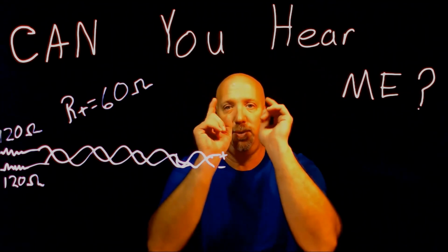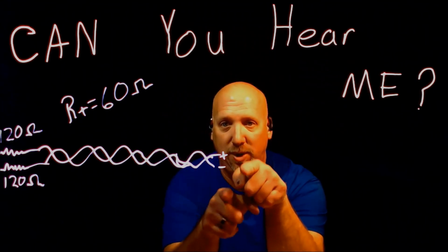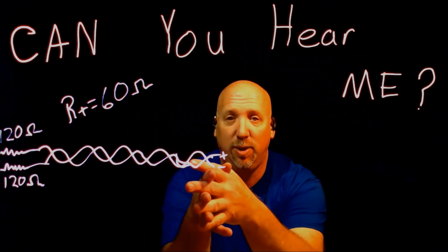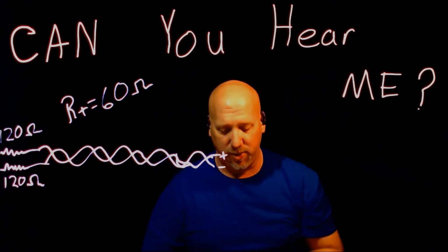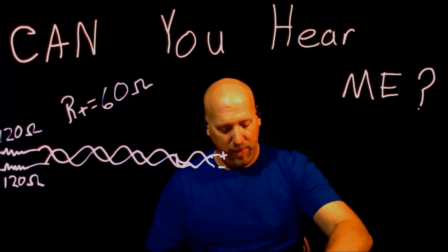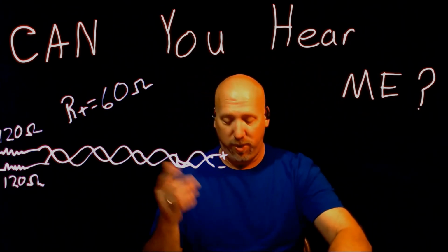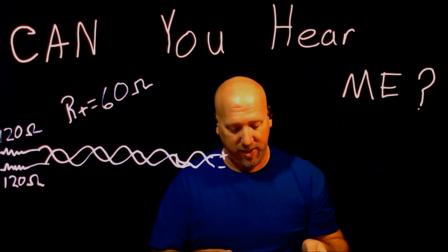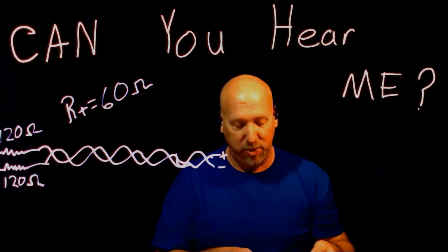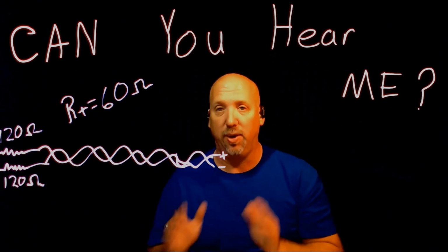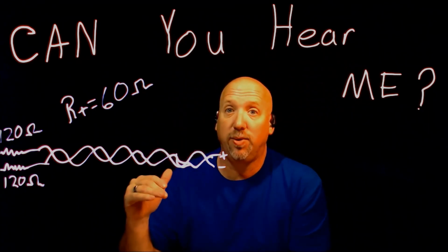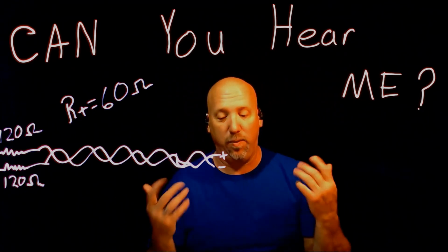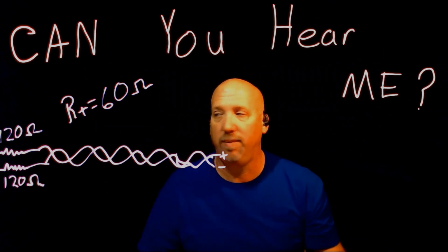You unplug the module, check your power and ground with your multimeter. If you have 60 ohms of resistance, you're good to go, and you go to step two or step three. But most CAN networks use dual 120 ohm resistors. There are some variations. The termination resistors may be located in specific modules. They also may be built into the junction connector. So it depends on which module you're dealing with, and service information will tell you which module to disconnect, how to disconnect it, and what wires to check. Be aware of that.